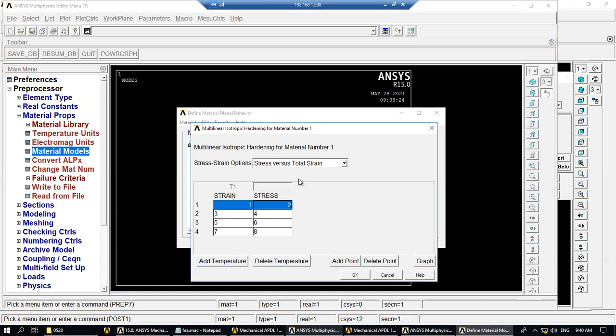You just input 2 something times 10 to the power of 11. If they are not matched, there will be no problem during the modeling, but when you start to solve your model, there will be an error saying these values are not equal. So the program stops. So pay attention to this one.